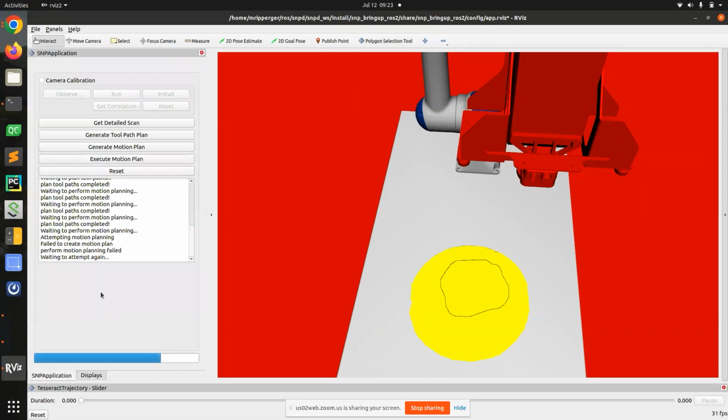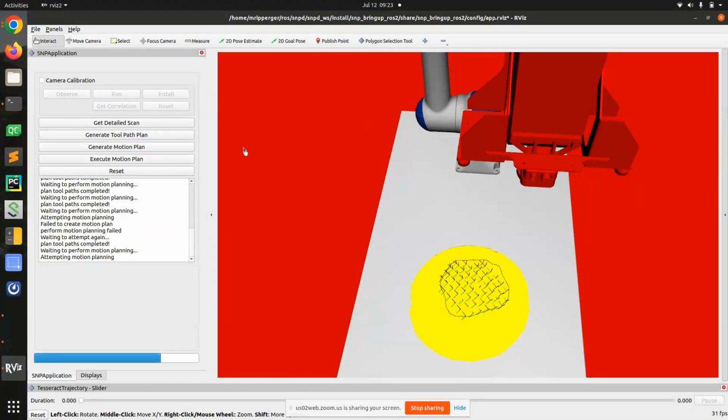And it'll run Descartes first on the rasters and then go through TrajOpt on each of them. Then it tries to connect the rasters with TrajOpt, or to join interpolated first if it can, and then TrajOpt if it fails that, and then OMPL if it fails that, and all run in parallel at the same time. And so hopefully it should run a little bit faster than it otherwise could have.